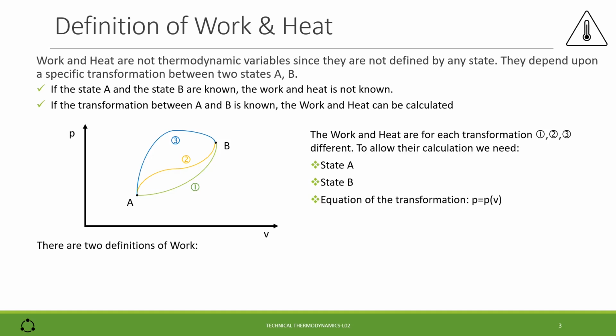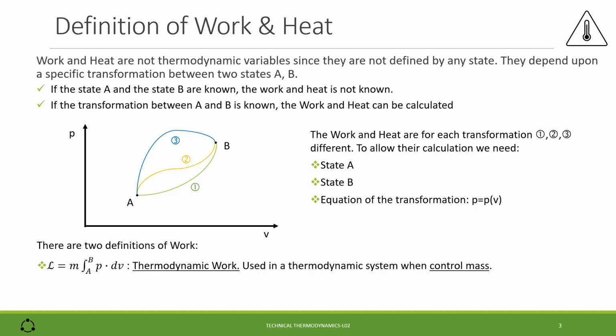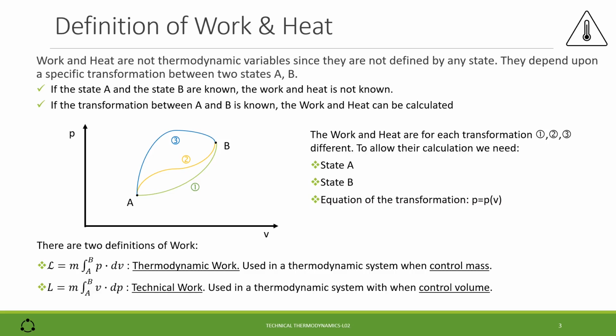There are two definitions of work. The thermodynamic work is used in a thermodynamic system when referring to a control mass, that is the integral between the two states of the pressure times delta V. The second is the technical work, used in a thermodynamic system when using a control volume, which is the integral between the two states of the volume times delta pressure. Of course, every integral should be multiplied by the mass.